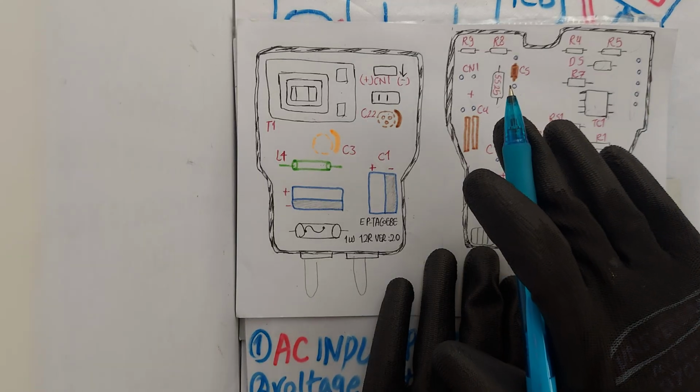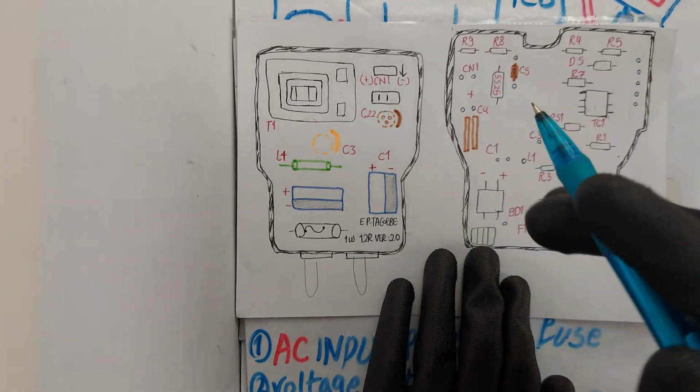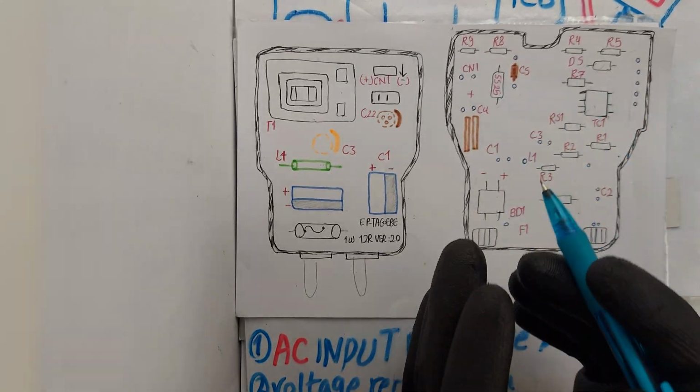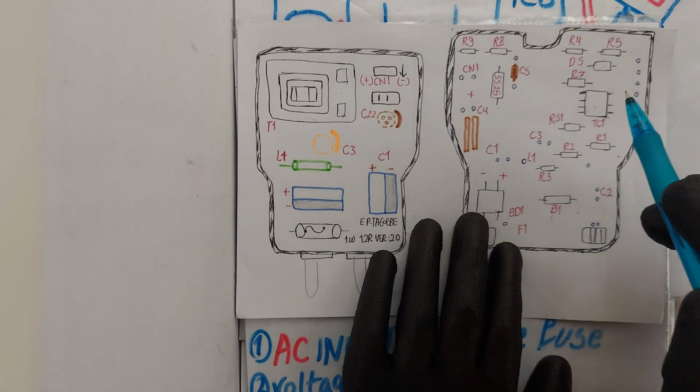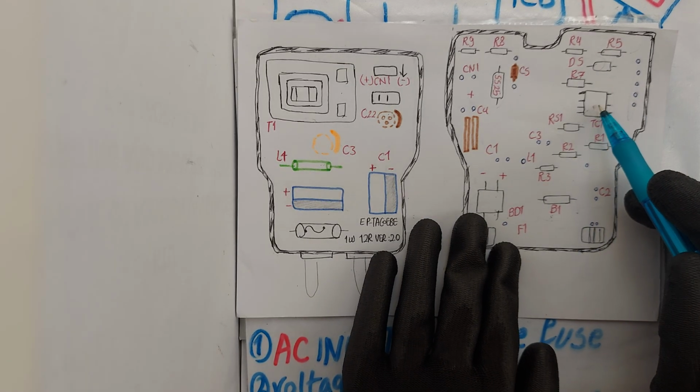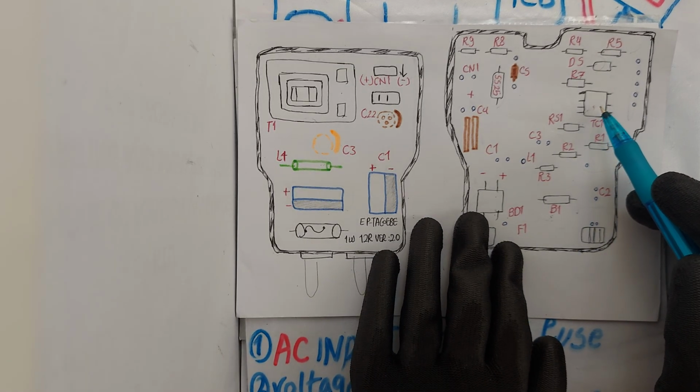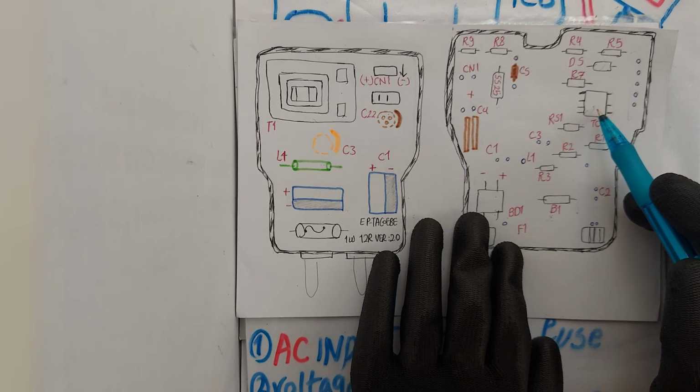The fifth step, feedback and output voltage regulation. The OB25133 control IC monitors the output voltage and load current, adjusting the pulse width, the ratio of the switch on time to off time.